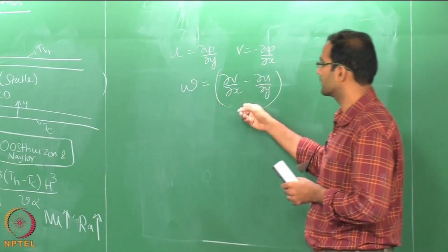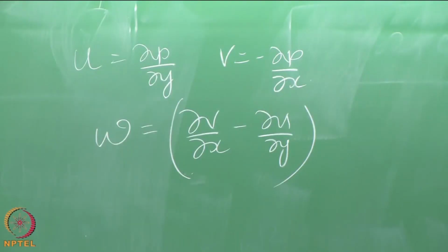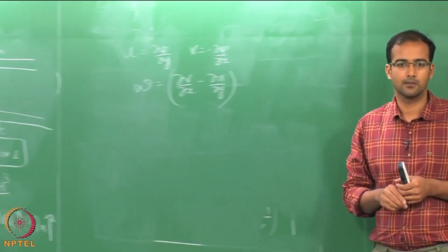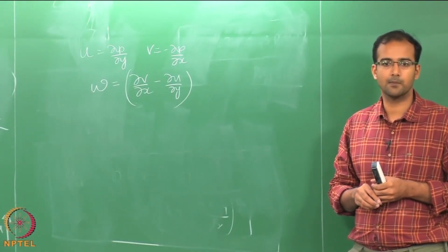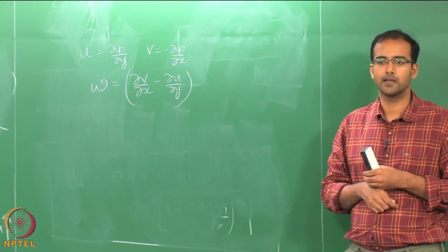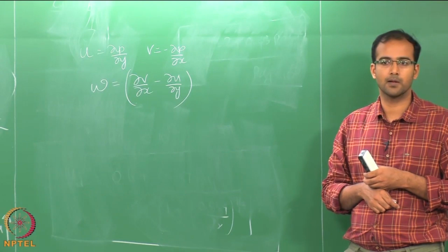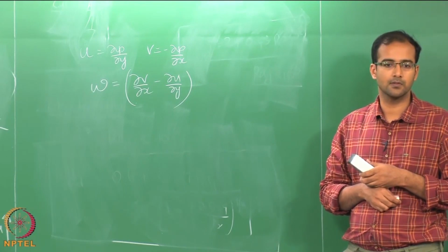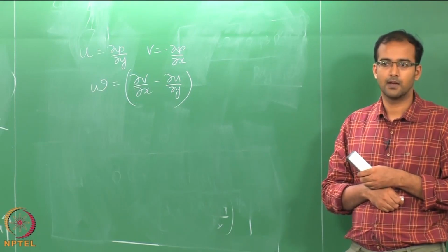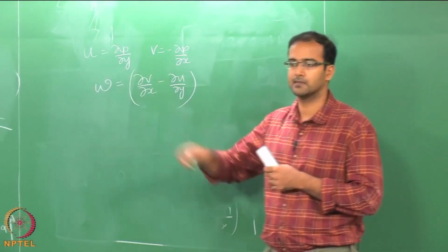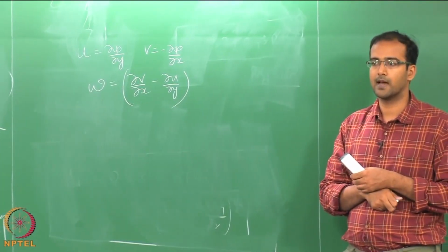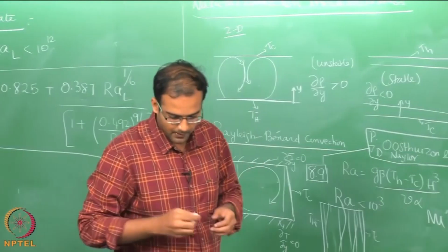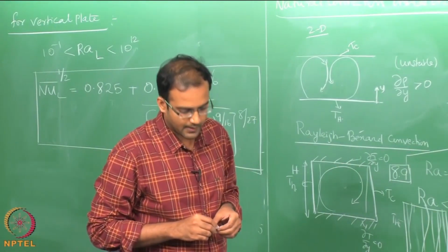So, you introduce the definition of your stream function, u = dψ/dy, v = -dψ/dx, and similarly vorticity, which is dv/dx minus du/dy. The Navier-Stokes equations, both the x and y momentum, are then rewritten. We do some manipulation there, for example, we take the derivative of the x momentum with respect to y and the y momentum with respect to x, and then we subtract. So, we can recast these equations in terms of a vorticity equation, and since the stream function satisfies continuity, we will have simple stream function vorticity equations which can be solved. The appropriate boundary conditions and the procedures are all very nicely explained.